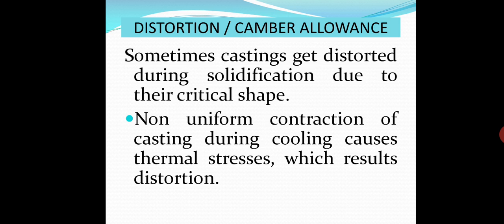From practice or experimental observation, this defect is pointed out. Non-uniform contraction of the casting during cooling causes thermal stress, which also results in distortion.